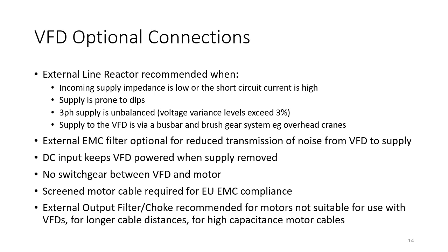The DC input I mentioned keeps the VFD powered when the supply is removed. So it's helpful if you want to set up the VFD parameters when the VFD is powered down, but you still want to do work on it. It can also be used for diagnostic purposes. As I mentioned, no switchgear is allowed between the VFD and the motor. For the European Union, for EMC compliance, we normally need a screened motor cable. That reduces the transmission of noise from the motor wires out to the outside world.